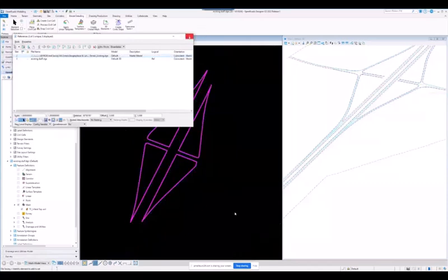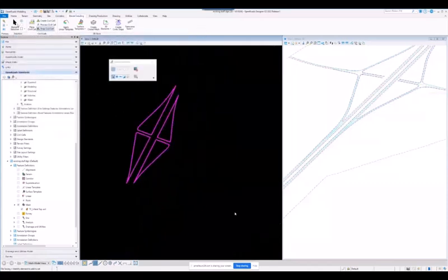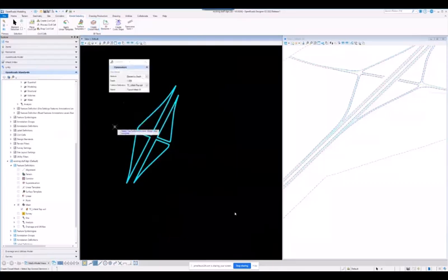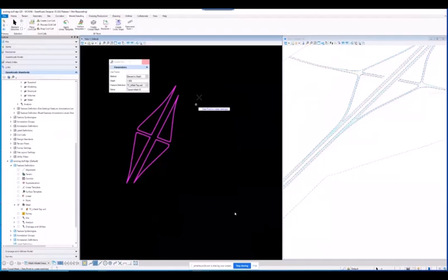It's a high cost. In this case, I want to pick this stuff up, and since I know it's between the existing pavement, I know that's topsoil in this area. I want to take a foot off, and now we have the ability to take selection sets. You just don't have to do one, then the next, then the next, then the next. I could have 50 of these shapes, 100 of these shapes. It doesn't matter. A lot of other functionality has been added here, but basically we're just showing the concept here. We're just going to take all 4 of these. We're going to pick existing ground. We're going to take the area, and then we're going to transform basically 1 foot down, and then we're going to encapsulate these meshes to create topsoil.